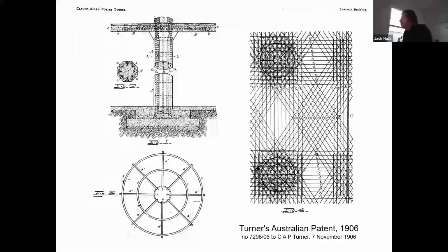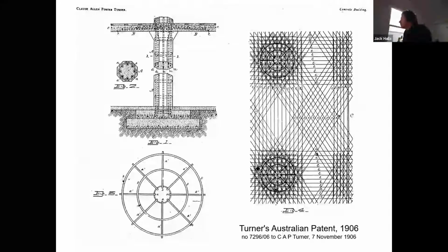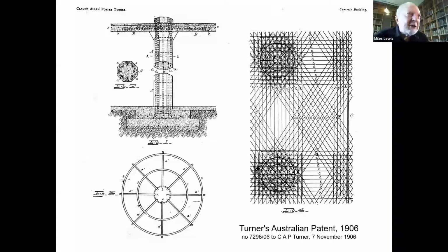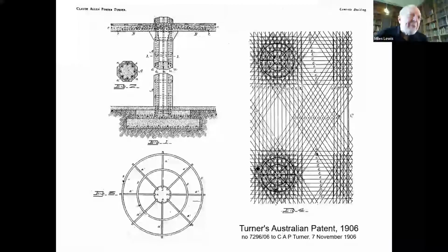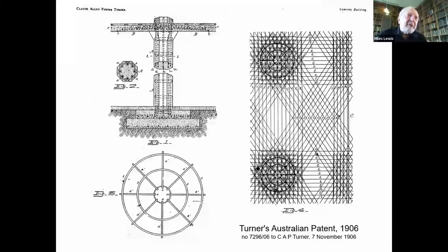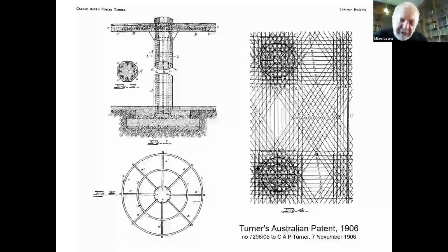Is it easier to build the formwork, more efficient? Absolutely, spot on. Formwork, circular formwork is very difficult. In more recent times, tubular cardboard is sometimes used to create formwork, but at this time that wasn't available. So building in timber, an octagon is far easier to form, and likewise even that the flared head far easier to form than the shapes which are being used in the American system.